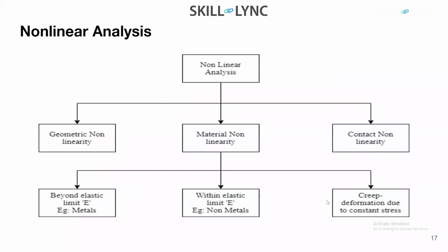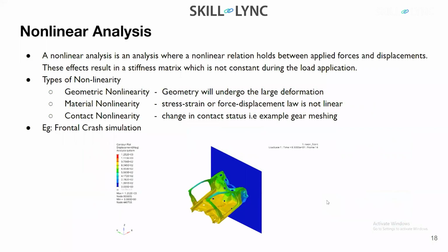Talking about geometric nonlinearity, any component which is going to undergo a large deformation will be termed geometrically nonlinear. And in any case where your stress-strain graph or the force-displacement graph is nonlinear, I'll say that my material is nonlinear, or I'll call the analysis type a nonlinear analysis.